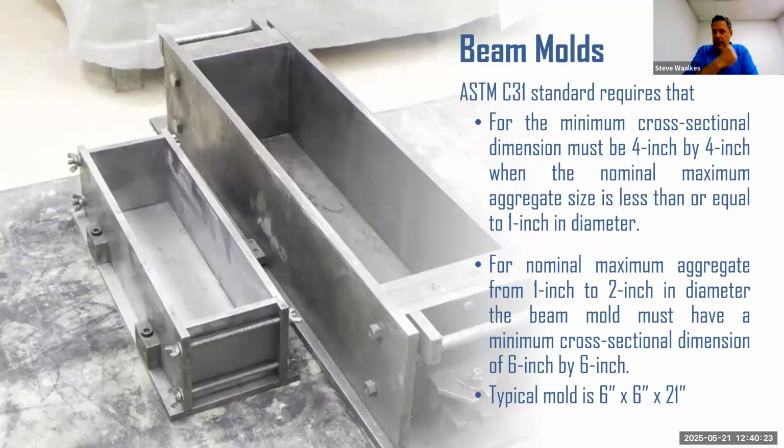Beam molds, you can be as small as 4 by 4 if you've got 1 inch diameter, but the standard is pretty much a 6 by 6. And then most of the break machines have an 18-inch spacing in the supports on the bottom. And then the load is either in the middle or split into third points from the top. But the supports in the bottom are typically 18 inches.